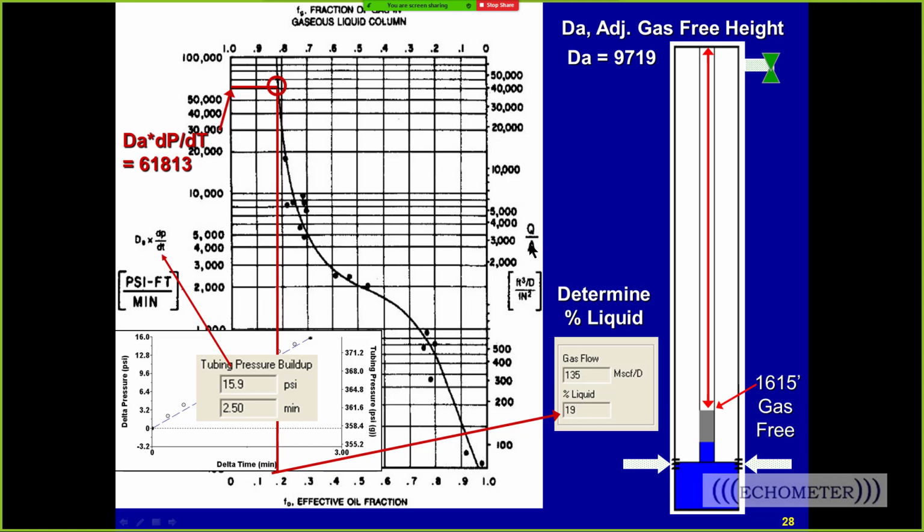This is gas volume over area, which is the gas velocity. So this is the gradient of the liquid when the gas flows at and below critical rate. So this is pretty good. I've got data where, with 4,000 foot of gassy fluid shooting down the tubing, the pressures are within 8 psi. I think it's fairly accurate. Really good. It's a good correlation for liquid load gradients.